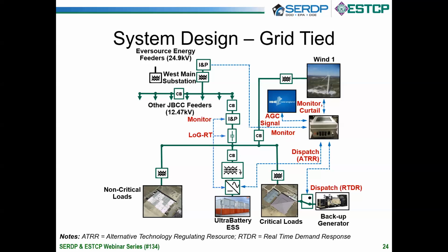And the reason we had to do that is because in order to get the interconnect with the utility, we had to agree to a relaying scheme that would require a particular level of power import, which is essentially derived from California Rule 21. So we couldn't allow the battery and the wind turbine to generate too much, otherwise it would cause the microgrid to be tripped into an islanded state, which is not really what you want to be doing due to a self-inflicted island that's unpredictable.